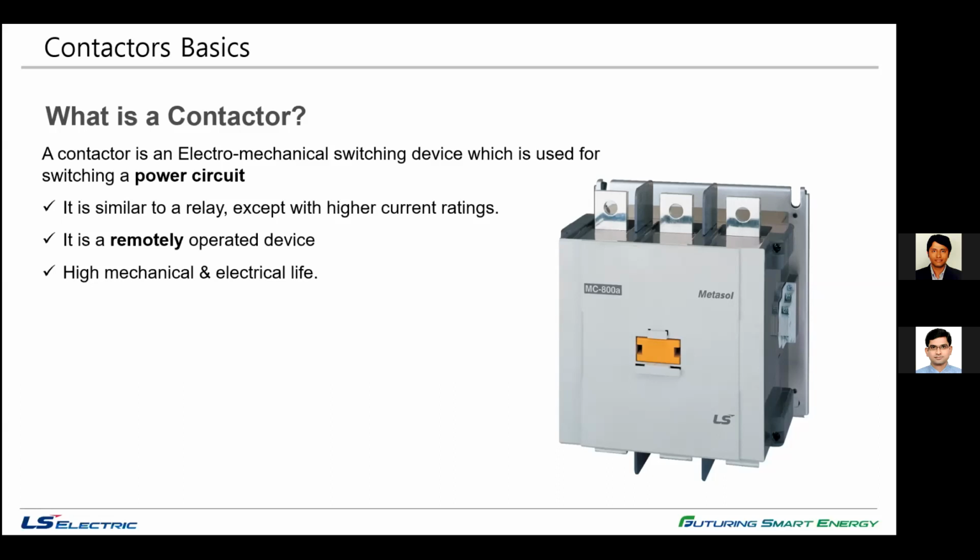A contactor is controlled by a circuit which has much lower power than the switched circuit. Contactors come in many forms, varying in capacity and features. Unlike a circuit breaker, the contactor is not intended to interrupt a short circuit current. But a contactor breaks currents from several amperes to thousands of amperes, from 24 volt DC to many kilowatts. In size, it ranges from small enough to pick up in one hand to large devices approximately a meter per side.